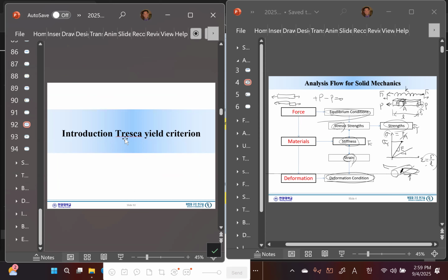And historically, there are many. They are also engineers like you. But they did a lot of experiments, combining combinations, considering all nine stresses. And then they found a certain rule. Oh, when the 9 component stresses reach a certain state, it fails. So it helps us a lot. We don't have to go through all the experiments. We don't have to spend a hell of a lot of time. We just follow the rule. So that's the failure criterion.